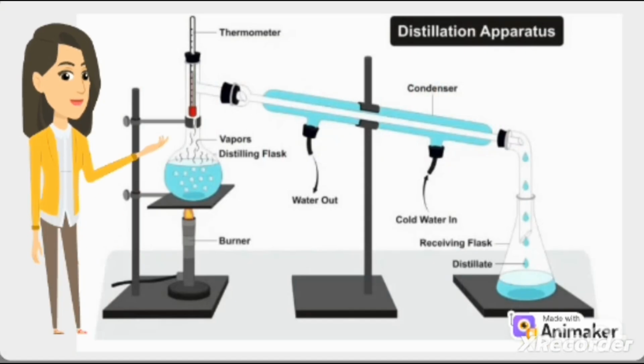In the early stage of distillation, the vapor, so the distillate, leaving the still is rich in the more volatile component, and as the distillation proceeds, the liquid in the still becomes lean with respect to the more volatile component. The composition of the less volatile component thereby increases, and hence the boiling point increases.